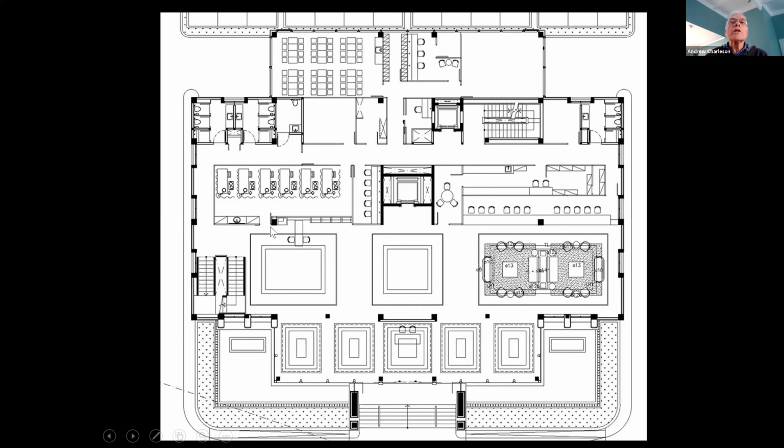This could be a moment resisting frame too, actually, because these columns are quite big. So we could have a 3-bay frame running through there with the bay lengths being different dimensions. And similarly, this could be a moment frame. But there's no other resistance in the Y direction. So for my design, I'm going to assume just 2 moment frames, one at each end of the building.